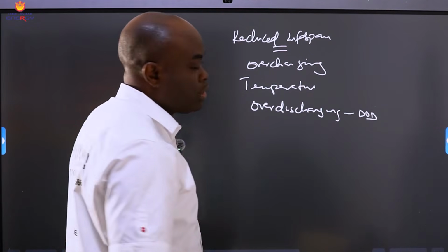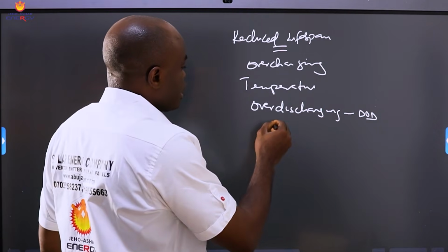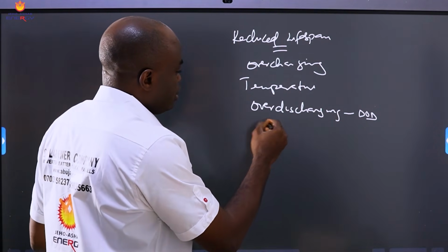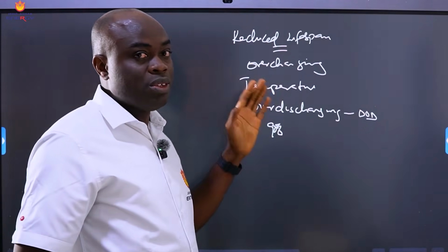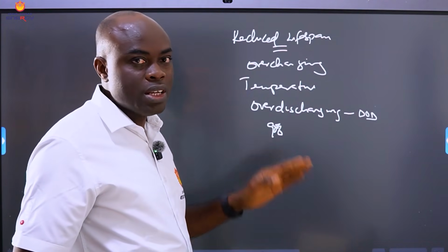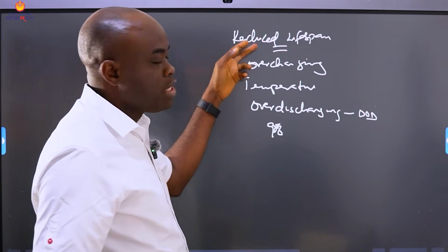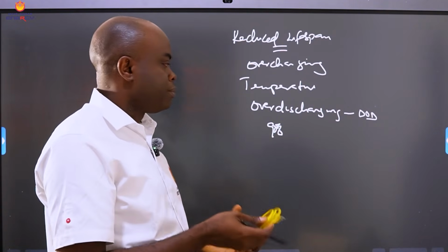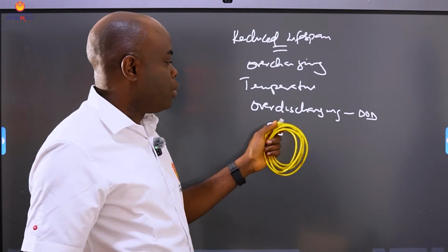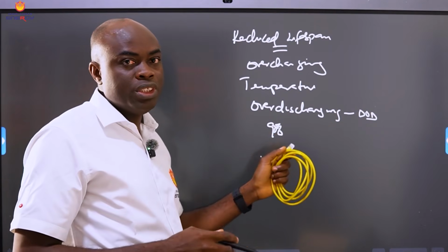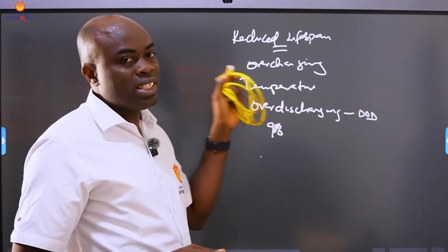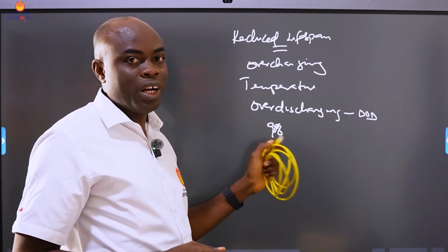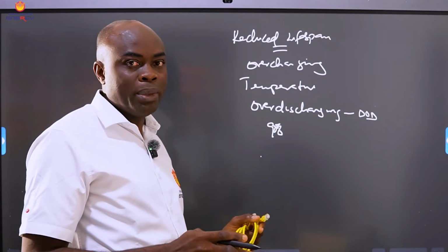When you over discharge, it's always recommended to discharge just 90% out of your battery, and if you keep discharging to 0, 0, 0, it reduces the lifespan. But with this communication cable in between, even if you don't program your DOD, the inverter automatically detects the manufacturer DOD set on that battery.